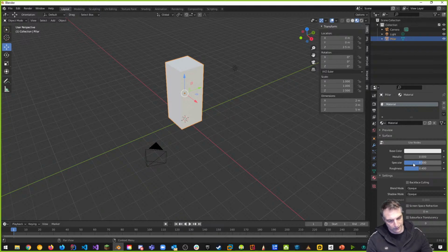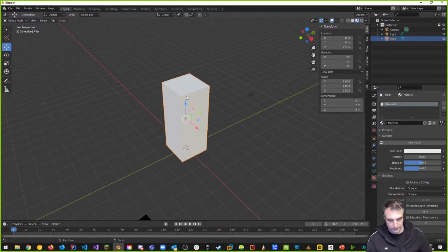It also talks about specularity, and I want you to think about specularity as reflectivity, if you will, as well as metallic, which is the metallic nature of the material that we're talking about. Right now it's 0. So if I wanted to make it more metallic looking, add a metalness to it, then I could increase that value. There's also a roughness, and I can increase or decrease that value to make it look like it should look. Okay, there's other options here too, but the ones I want you to recognize are that I've got a material that has a certain color that I've applied it to, and this is the base color, and the base color is something that we can add on, and we can modify, we can layer color on top of this one, to create an effect that we want.